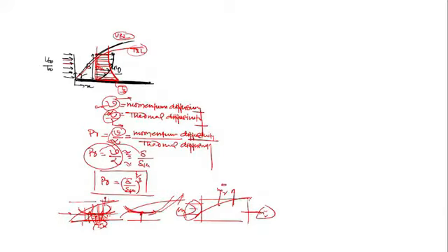In the fluid mechanics problem, we solved one problem. Whatever mass entered through this, some of it flows through this and some goes out through this region, outside the boundary layer. So since mass is going out, along with the mass, energy will also go out. So whatever heat gets conducted into this layer will be swept away downstream, and finally what happens? It is transferred to the fluid outside the boundary layer.